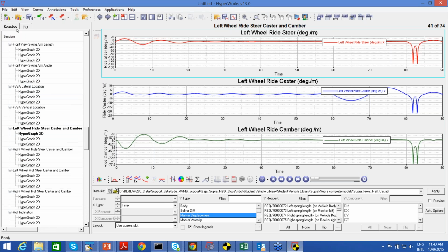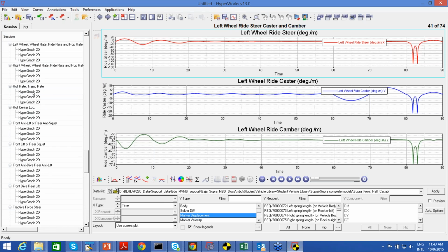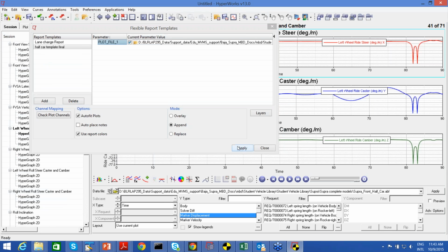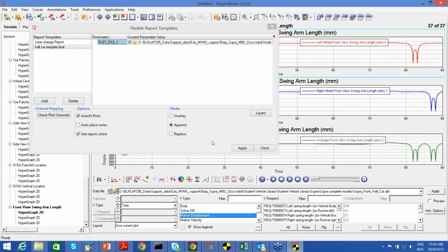Okay, so this is what we have performed to understand the suspension behavior in terms of kinematics and compliance simulation. What we have observed here are the wheel vertical forces, caster, camber, toe angles, caster trail, mechanical trail, and we can also plot wheel vertical displacement with respect to the wheel forces. If you want to change any output with respect to the wheel displacement, you can change that too. I'll show you one of them.